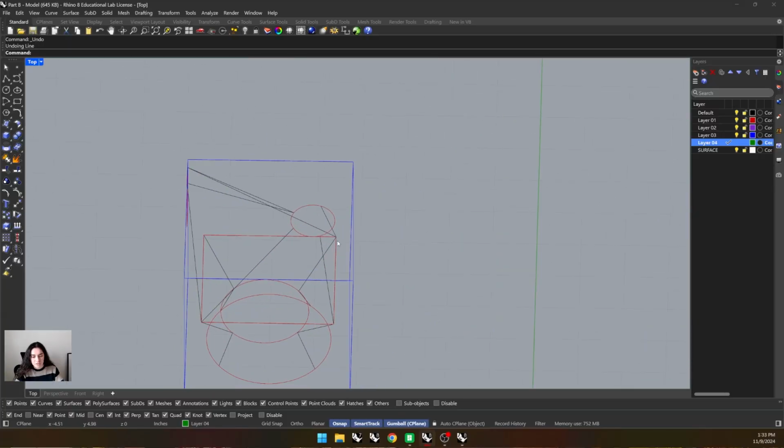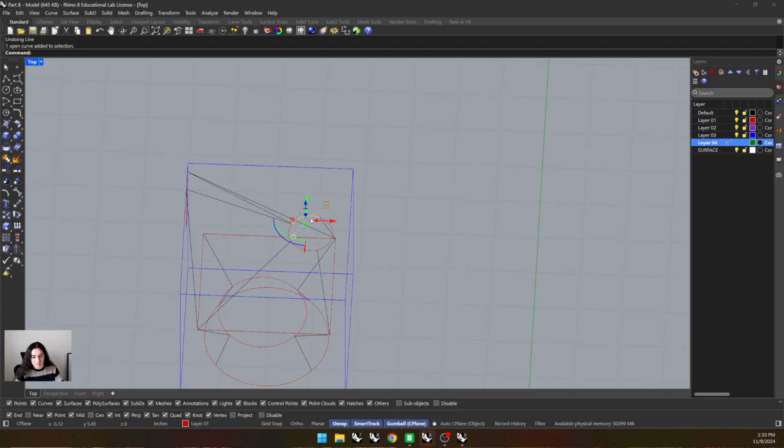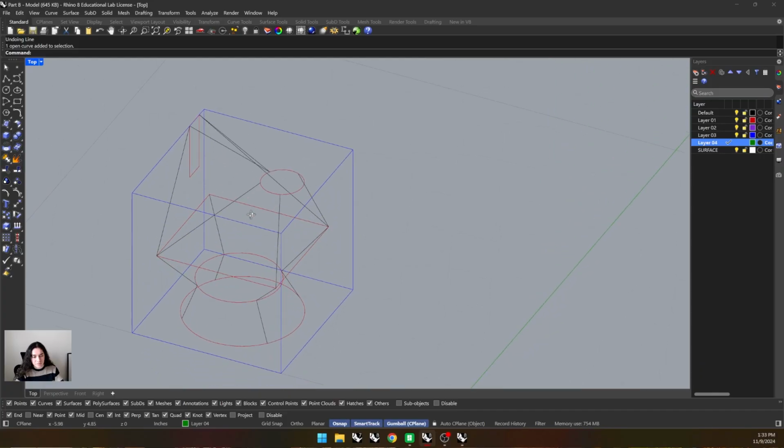Great. The next thing I did is I made sure to, if I'm working with a circle, because I'm using the command, not using patch, either surface from 2, 3, or 4 edge curves or a network surface, I needed to make sure to have some of these shapes exploded or sliced so that my circles split up into 4 quadrants, sort of.